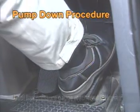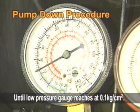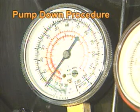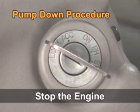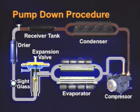And then push the accelerator pedal until the low pressure gauge reaches 0.1 kilogram per square centimeter. As soon as it reaches 0.1 kilogram per square centimeter, you should stop the engine. In this condition, no refrigerant is in the low pressure line.